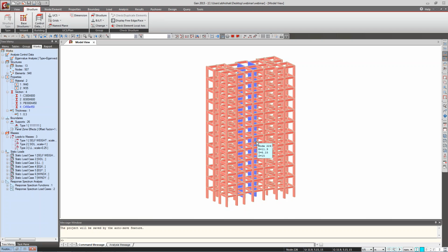So you only have to mention the plate. If you consider the plate, it takes the in-plane, out-of-plane and rotational matrix. If you say membrane, it only considers in-plane and rotational matrix. These are some differences from other software. In other software, you have to mesh the slab or the wall because you want perfect stresses and this type of contour. But in our software, there is no need to do this. The program automatically takes care of it.